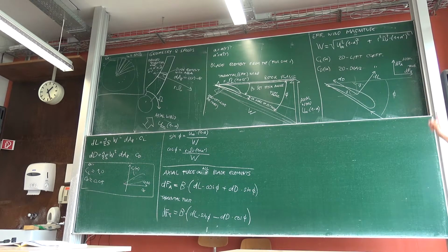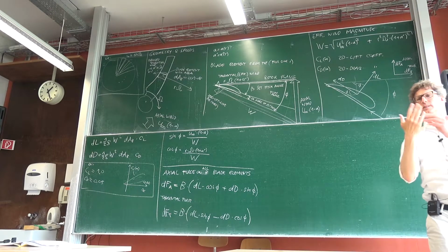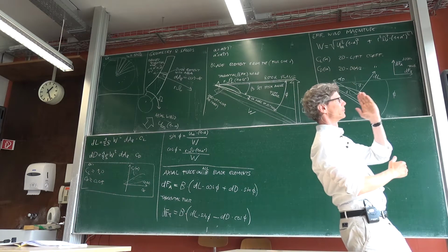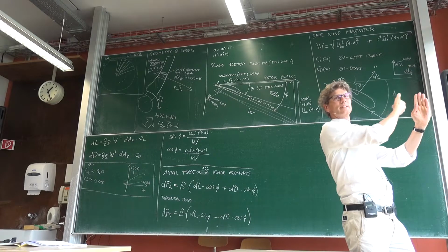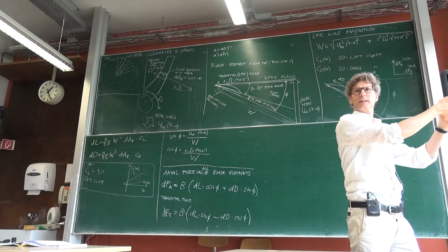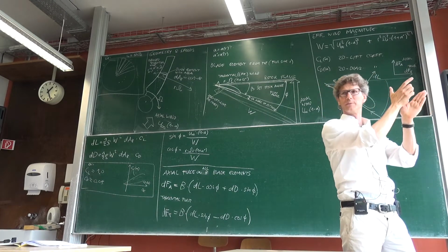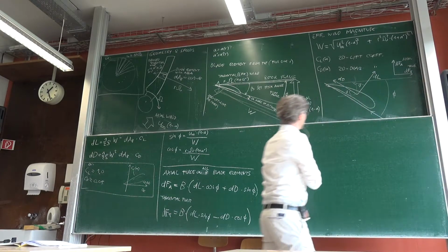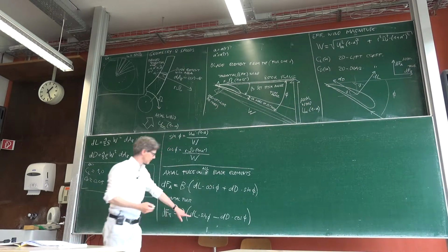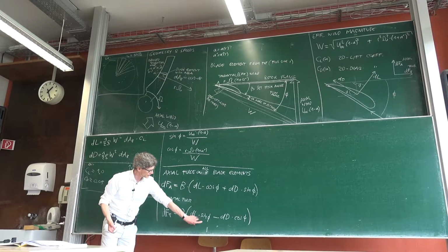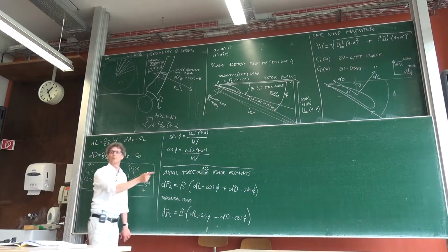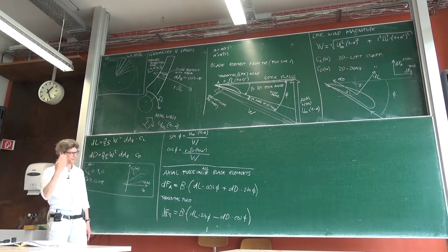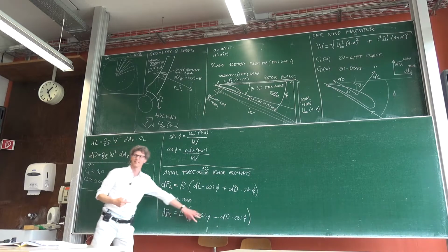But the force in this direction, there will be a force. If I have my wind turbine, I have my blade, sorry, this is maybe the better blade. So the blade moves in this direction, gets wind, yeah? And it gets a force in this direction, and it gets a force in that direction, right? So actually both numbers we expect to be positive. Of course, this all depends on the angles and so on, but in a normally operating turbine, this number must be bigger than that one, right? So that we get pushed forward and not backward. If we want to destroy energy, we would just have this negative.